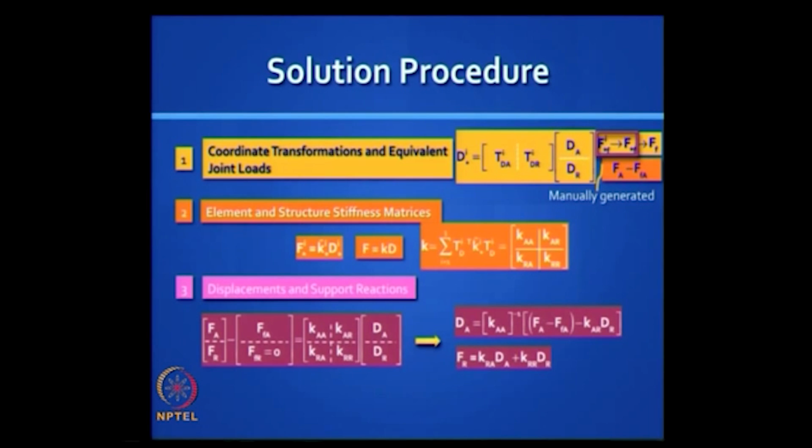So if you want, you can find the support reactions along with the unknown displacements, and you need to find the membrane forces. This last equation is similar to your slope deflection equation, except that you are now including the contribution, if any, of axial deformations, right.